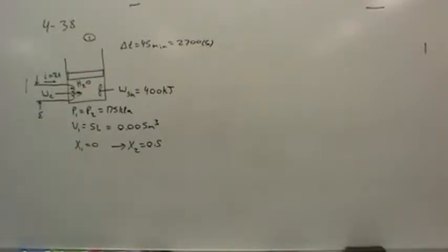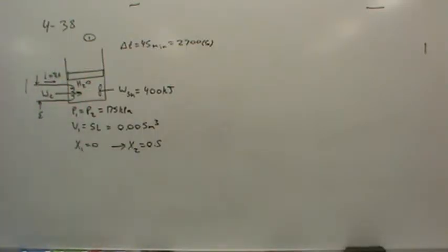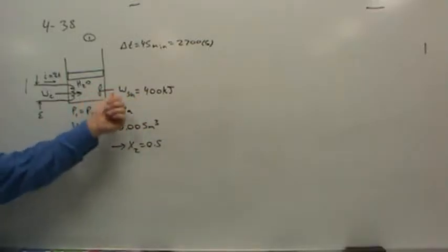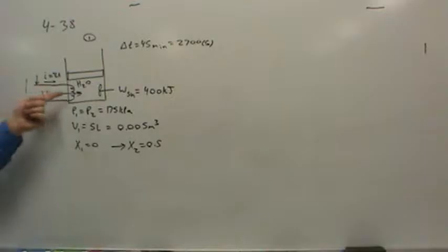Okay, now, before we jump into a bunch of equations, let's think about this and try to see if we can come up with some answers on our own. Let's try to understand what's going on rather than just throw a bunch of math and equations at it and hope it works. Okay? So, if the water evaporates, did the water gain energy or lose energy? It must have gained energy, right? Now, where did energy enter the system? Well, there's some work that came in here that's shaft work. There's also some work that came in that is electrical work.